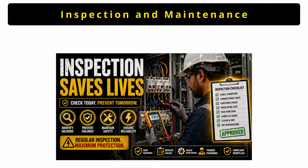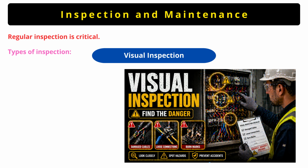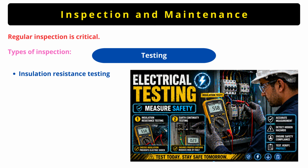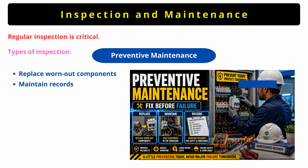Now let's talk about inspections and maintenance. Regular inspection is very critical. There are various types of inspections we can do. The first one is visual inspection. In visual inspection you can check whether the cable is damaged or not, whether there are any loose connections, or any burn marks. We can check this visually. The second is testing. Insulation resistance testing we can do, earth continuity testing we can do. And third one is preventive maintenance. If you find a wire in damaged condition, you can replace it, replace worn out components, and maintain records. That is preventive maintenance.